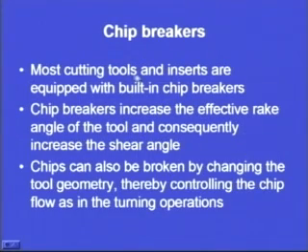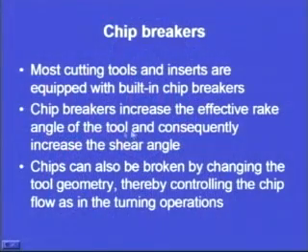Now, most cutting tools and inserts are equipped with built-in chip breakers. Initially we used to apply a piece of metal at the rake face of the tool, but presently most cutting tools and inserts are equipped with built-in chip breakers. Chip breakers increase the effective rake angle of the tool and consequently increase the shear angle. This is what we will discuss when we study the mechanics of cutting.